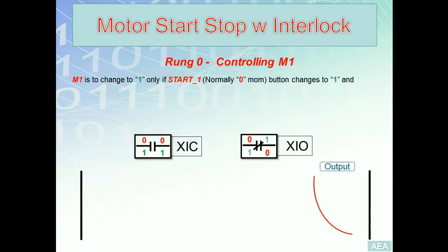As you recall, each rung consists of 2 sections, an output section and an input section. As this solution for this requirement is controlling M1, it means we need to add an instruction among the output section that refers to M1. The only instruction that we have covered so far is an OTE, and this concludes the first part of this requirement, choosing OTE for M1.